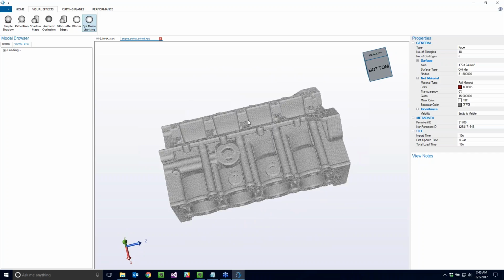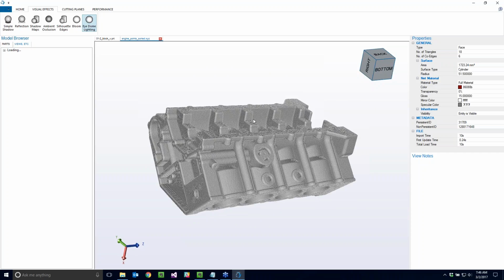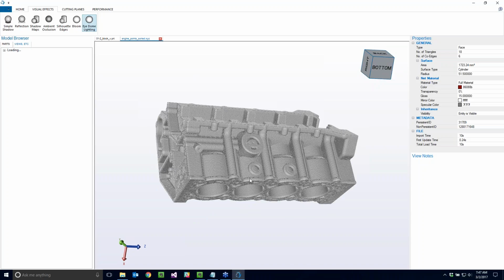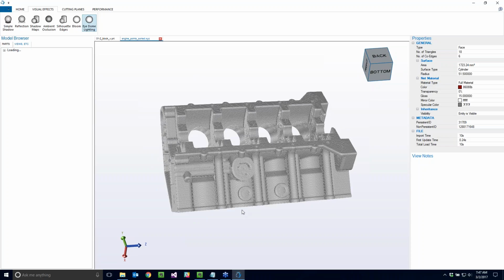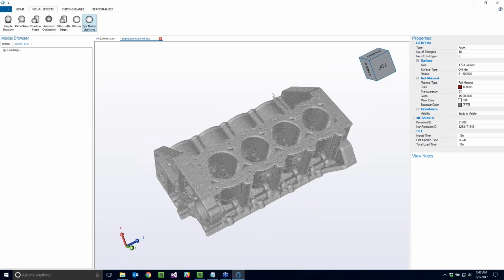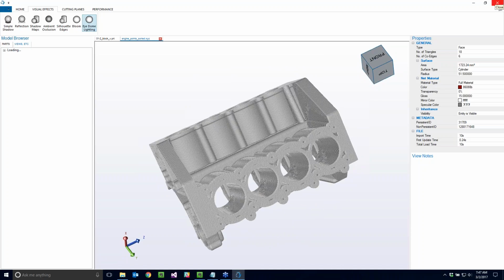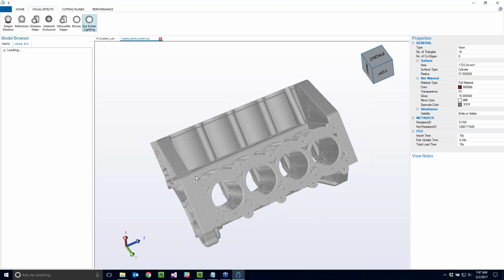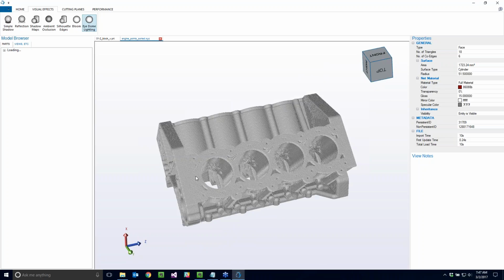Well, with some of our advanced shader techniques, we're able to infer a normal, or how light bounces off those points on a surface, and all of a sudden I'm able to get, again, depth information, visual cues that are so important to be able to interrogate a particular object, when I apply this eye-dome lighting technique onto that set of points. And all of a sudden, now it's data that I can start to work with and maybe measure, interpret, or project onto the original surface and do a deviation measurement from that.